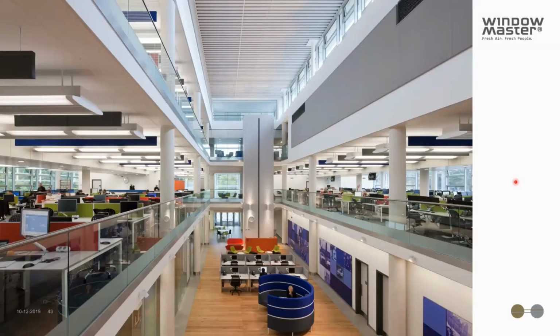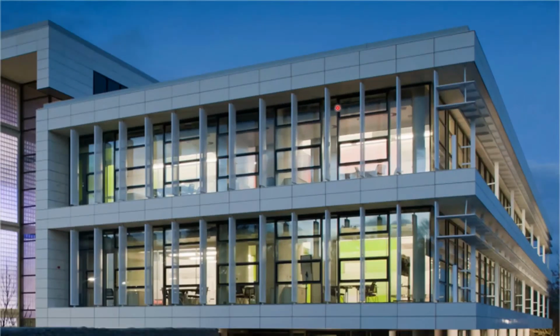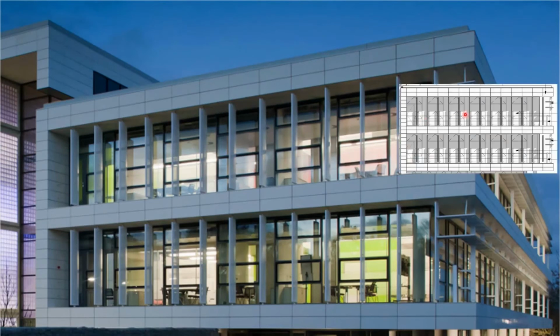You have a central atrium with open office areas on both sides of the atrium, and you have the operable windows in the top of the atrium, which should work as the exhaust for the old air coming through from the open office spaces. On this picture, you can see more clearly the facade design of the building. If we zoom in a little bit, you can see they have both high-level operable windows and also medium-level operable windows. So it's a really optimal design for natural ventilation.